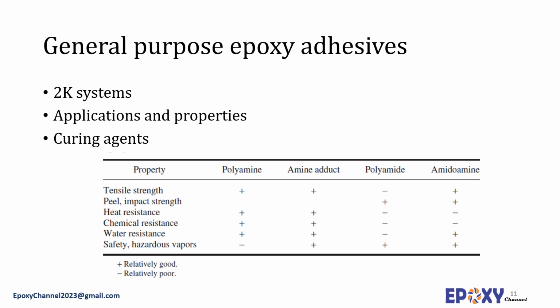General-purpose adhesives are suitable for bonding various substrates used in construction, such as wood, stone, brick, metal, glass, rubber, plastic, ceramics, etc. These adhesives, often two-component solvent-free materials, show exceptional adhesive properties on cure and are suitable to fix damaged items which require a fine glue line. Curing agents for general purpose two-part room temperature curing epoxy adhesives include polyamides, amidoamides, and aliphatic amines. Polyamides and amidoamines confer flexibility and a degree of toughness to the cured epoxy, whereas the more reactive aliphatic amines provide moderate temperature performance but good chemical resistance. Properties of curing agents used in general-purpose epoxy adhesive have been presented here. Based on the data presented here, a suitable curing agent can be used in the formulation for a certain application.